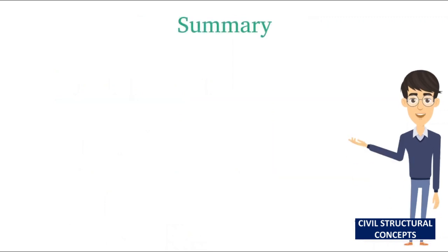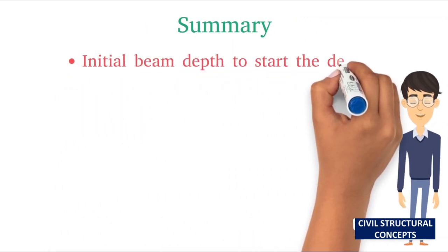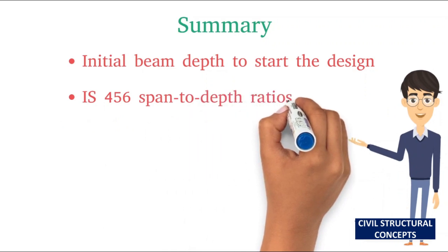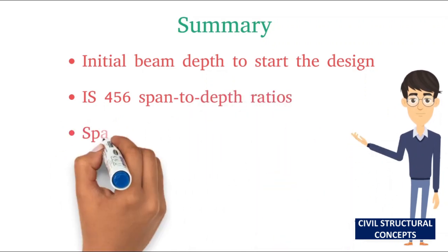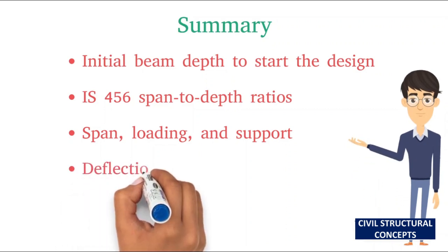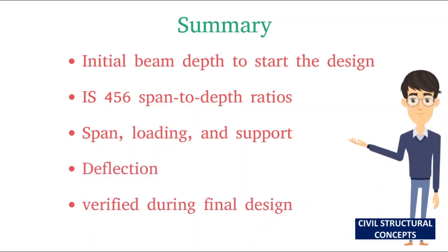Let us summarize. Initial beam depth is required before starting the design process. It is based on IS 456 span to depth ratios. It depends on span, loading, and support conditions. It helps in controlling deflection. And it must always be verified during final design.